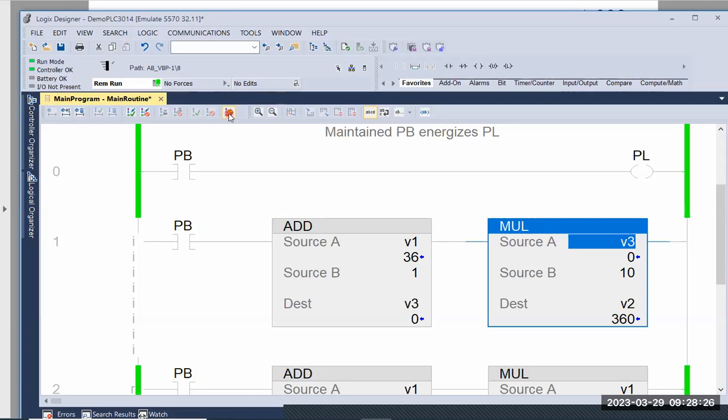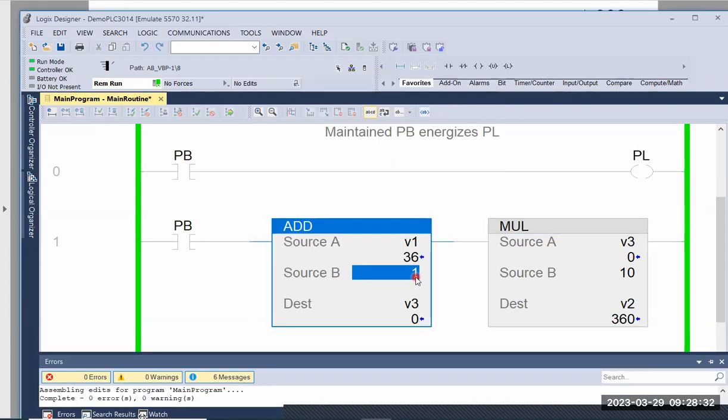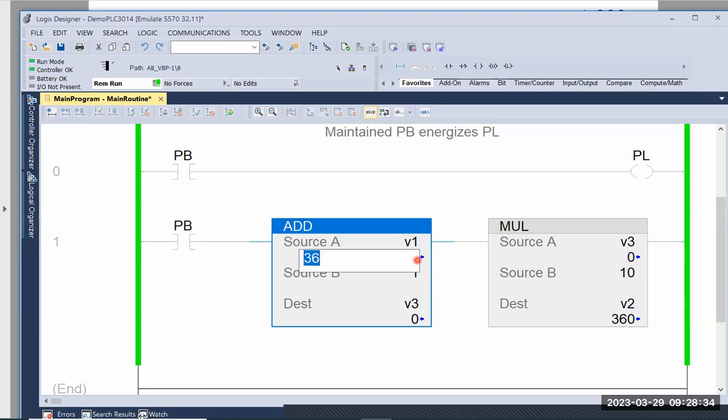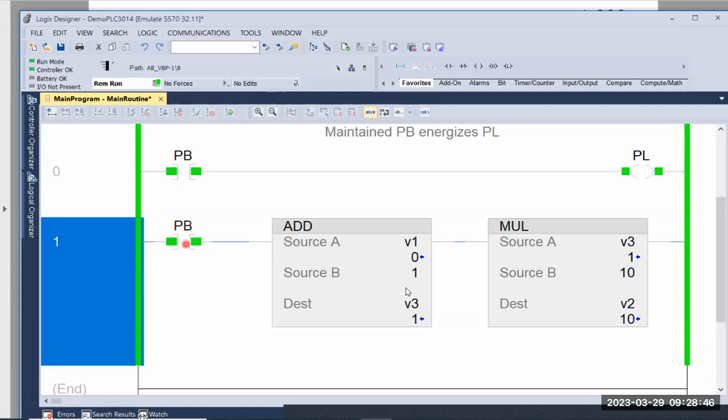So if we try that, let's see what happened. If we change that, clear that back to 0. Let's try if we toggle that. You can see here, I even keep the button on, it's still true, but this is 10. That's exactly what we want. Even though the button is still true, it doesn't have a loop. We break the loop by using the intermediate result tag.